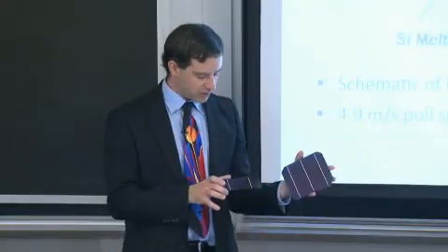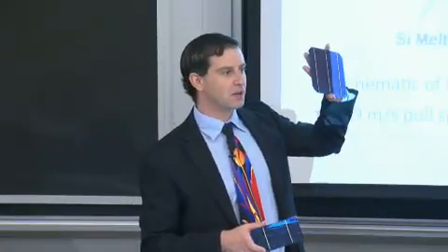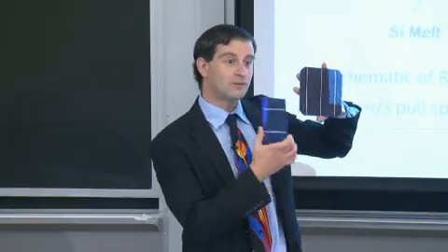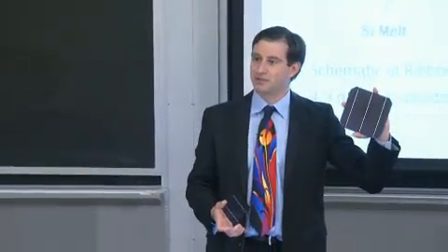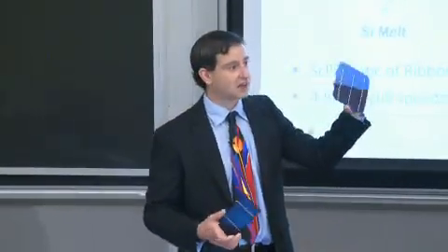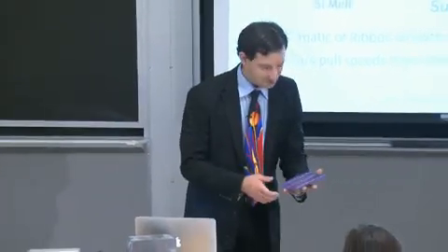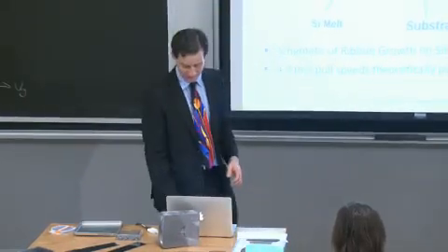Yeah. So the bus bars, the optimization of these bus bars, this one has 3. That's really to minimize series resistance, because now out of a larger wafer you have so much current being generated flowing through it that the series resistance through those very thin metal wires would end up resulting in large power losses, essentially heat instead of electricity. And so they added the 3rd bus bar, even though it increased the shading, to reduce the series resistance losses. So you can see these optimization problems are used quite frequently in solar.